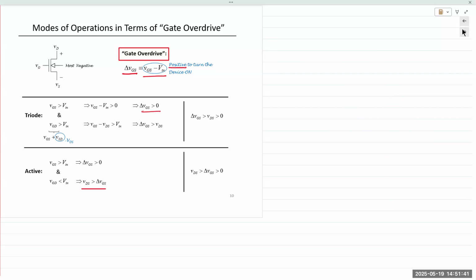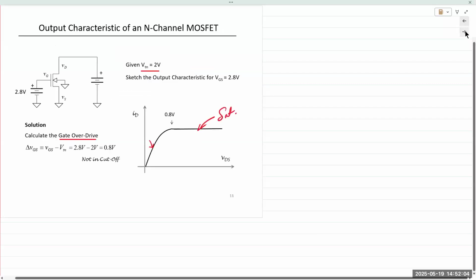Well, the first procedure in that lab is where you apply a VGS, gate source voltage, and you sweep the voltage between the drain and the source, obtain a set of data, and we can extract information about the threshold voltage for that device. We can do that by applying voltage at the gate and at the drain.